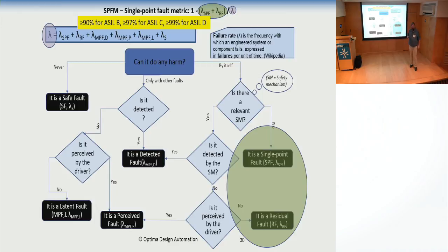There are pitfalls in this formula, and some people are even silly enough to try that in real engineering. They say, okay, I will add, for example, memory which is ECC controlled and therefore has a zero probability of failure, and then I will dilute the problems. Well, for that, there are other complementary metrics that will catch it. For example, going back to the FIT, what is the probability of a problem happening?